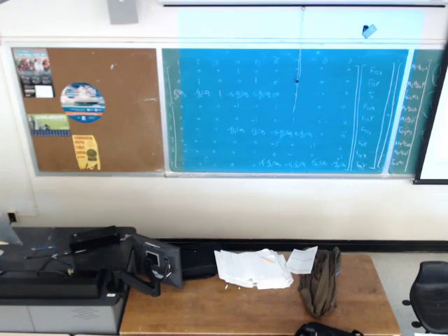And we would like to find the shaking force applied to the ground at joint O2 and O4, I'm looking for these two, versus the input angle. So I would like to see a graph, here theta, here F12. Theta going from 0 to 360, you find me the shaking force. And find the maximum shaking force at point O2 and O4. That's what would be the maximum value for the shaking force.